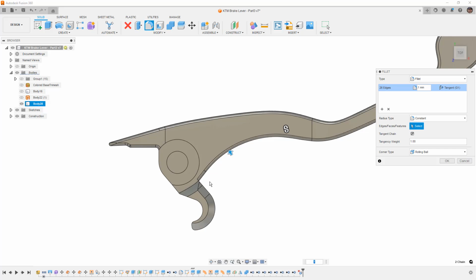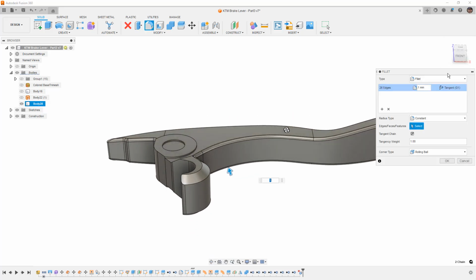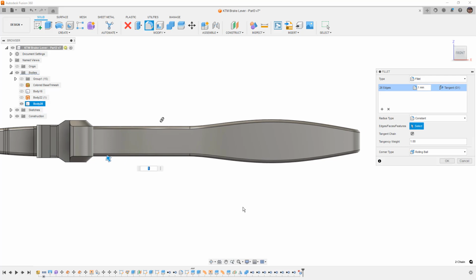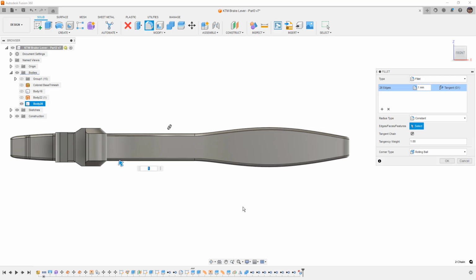Not that we couldn't do it if it was a spline, but it's just going to be easier in terms of manufacturing. This section here is a true arc. This was a true fillet. It's relatively small, but it is a true fillet. Now the ones on the outside here are going to be blended. And if there is a consistent radius here, we could potentially use a corner rounding tool. But because when we rotate this thing around it's not planar, tools like that generally aren't going to be nearly as effective. So it would need to be done with something like a scallop or a flow tool path.